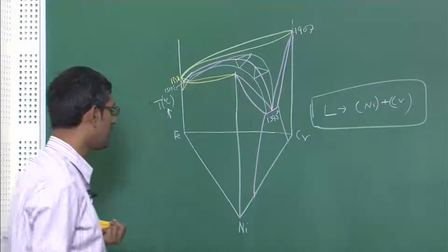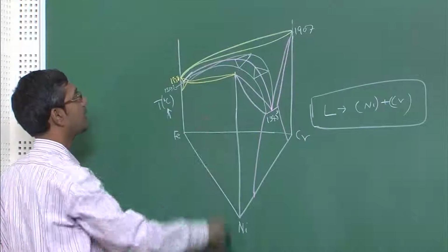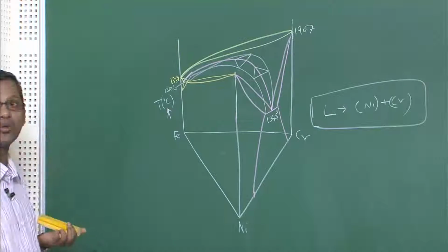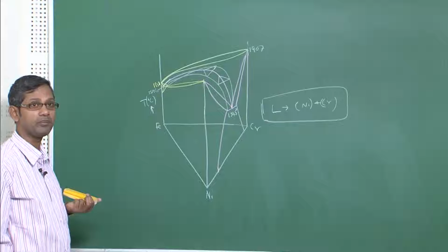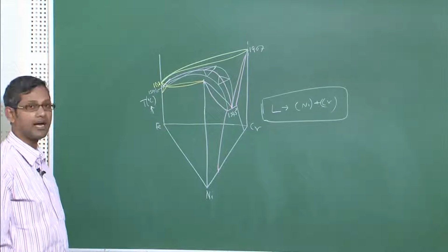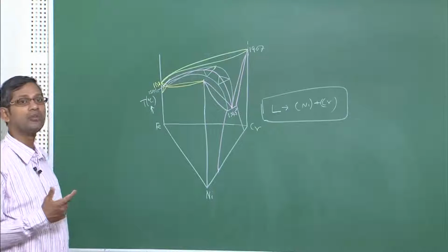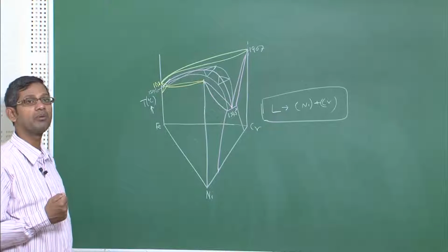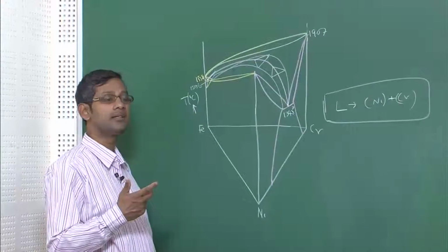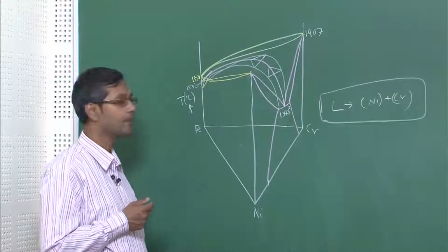The stainless steels actually are iron rich compounds, so they lie somewhere there actually. So, in most of the cases they undergo the peritectic reaction, that is what you should remember. But there are different types of stainless steel. If the stainless steel contains a little bit higher amount of nickel, then the peritectic reaction usually happens. In fact, that is why the basic problem of most stainless steel is the welding. In case of welding, the stainless steel undergoes this peritectic reaction and forms a lot of cracks.